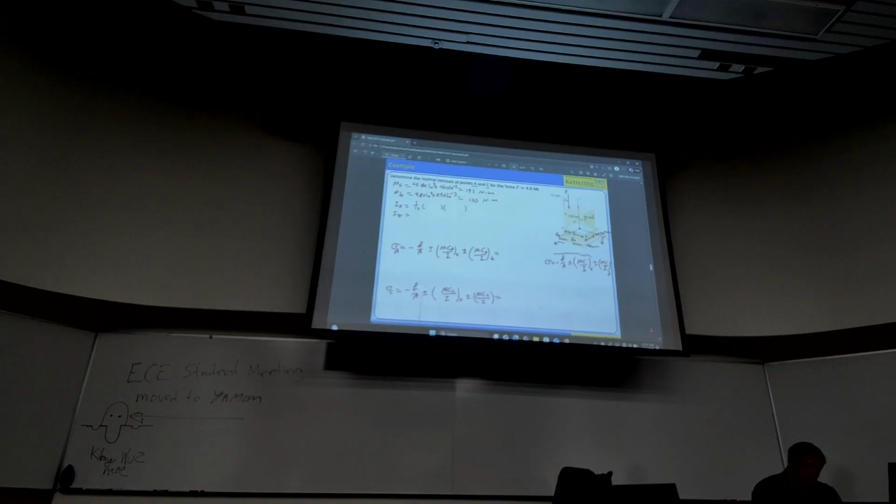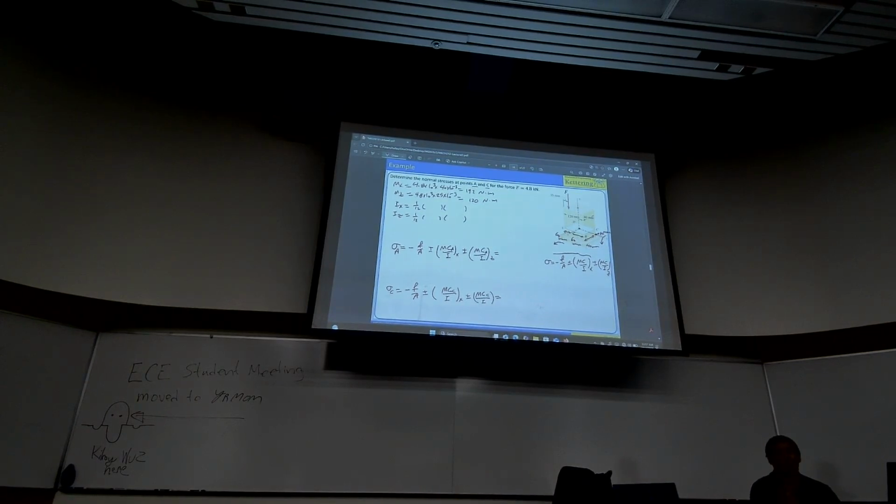The base and height are the same thing, right? Give me base and height, please. 120 times 10 to the negative third, and 80 times 10 to the negative third. And you see that figuring out which one is base and which one is height in 3D is not unique. That's why I said memorize it this way. The textbook says b h cubed or b cubed h, we don't know which one is b and which is h. It matters how we define that. But if you say it comparing this to that in 3D, it's always clear.